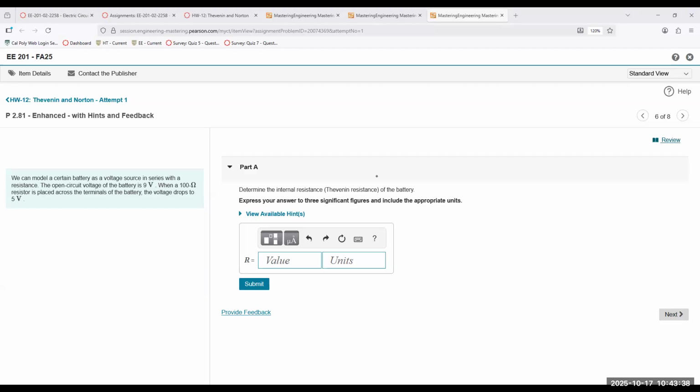So instead of using a voltage source with Thevenin resistance, you could represent the same thing as a single current source between the same terminals. The resistor this time would be in parallel.